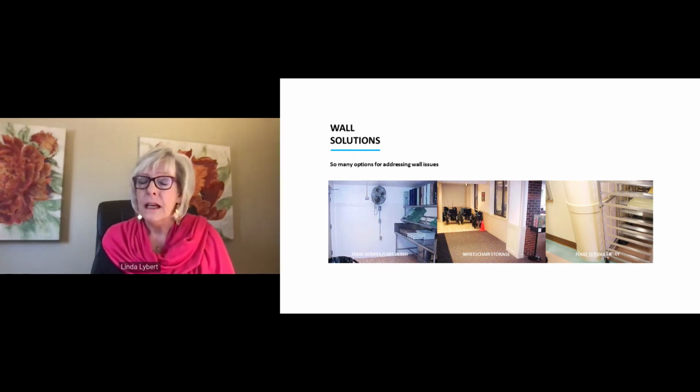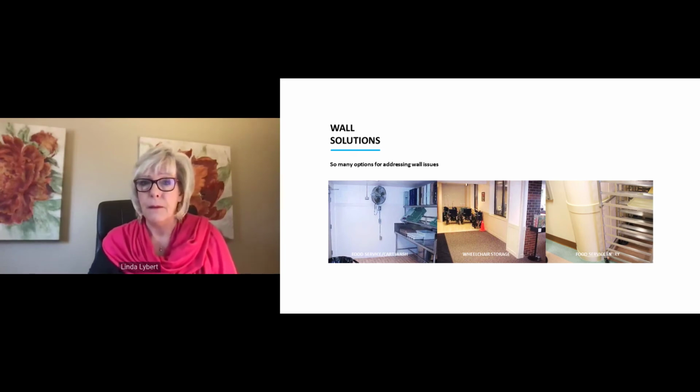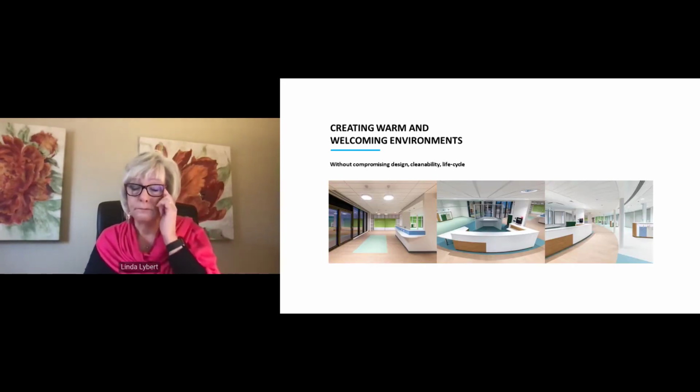And the center picture is in a high traffic hallway. It's actually in an entrance and not necessarily planned to be a wheelchair bay, but we had to deal with wall damage. And so we put solid surface there. And then the same with the food service cart area. If you look at how that food service cart is lined up with the wall, you can kind of see what areas were being damaged. And so this completely solved that problem. Yes, it was nicked periodically, but again, you can easily repair the solid surface material. But you've also addressed a cleanability issue.